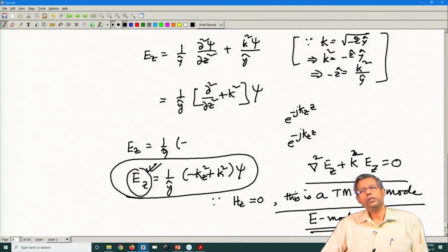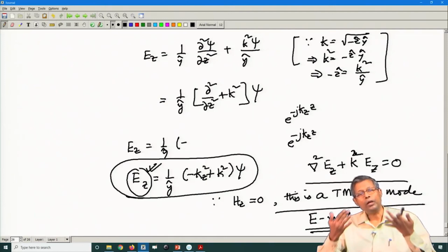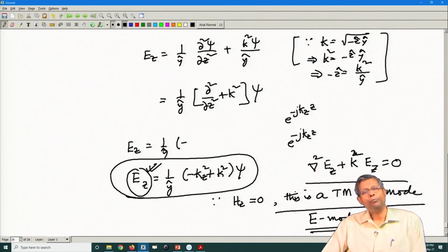But the same modes, the TE to Z or the TM to Z, will not satisfy the boundary conditions for a partially filled rectangular waveguide, which is partially filled with a dielectric. There we have to invoke another type of mode set, depending on the type of the discontinuity or the type of the boundary condition of the dielectric.